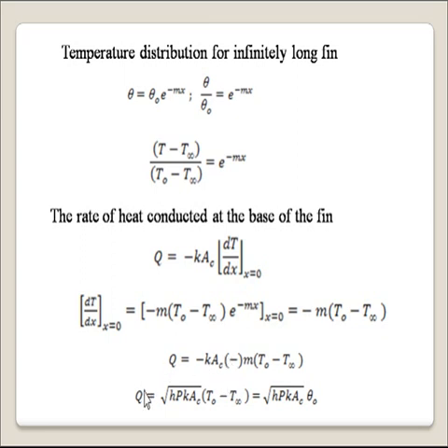By further simplifying, we get the equation of heat transfer rate, Q equal to root of hPkAc times T naught minus T infinity, where T naught minus T infinity is theta naught. So heat transfer Q equal to root of hPkAc times theta naught.